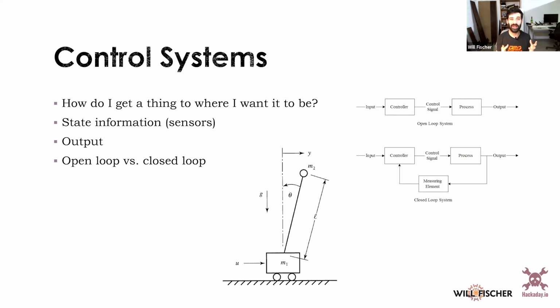And that's still not exactly closed loop control. Ideally, you have something like a rotational encoder on there that tells you exactly where you are at all times. So as you try to move to a specific location, you know when you're getting close and you can slow down before you get there. Because remember, inertia is kind of the enemy of your control system. It's going to try to keep moving even after you stop moving. So if you move to the location and then stop your motor, it's too late. Your inertia is going to swing you a little bit past.